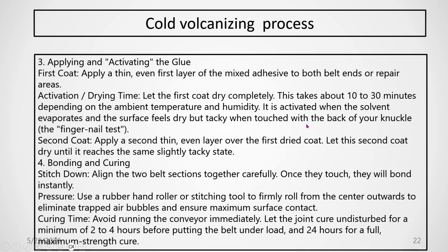When touched with the back of your knuckles, apply the second coat, an even layer over the first dried coat, and let the second coat dry until it reaches the same slightly dry and slightly tacky state.